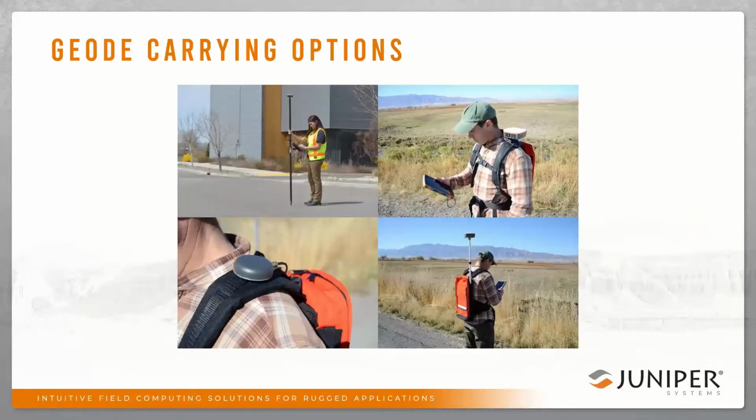The Geode, there's many different ways to carry the Geode. The top left picture is a standard, probably most popular way, with a survey pole. The Geode's mounted on top of the survey pole, and then there's a clamp that clamps your tablet to the survey pole. So you carry the survey pole with one hand, and then you have your other hand free for data entry.